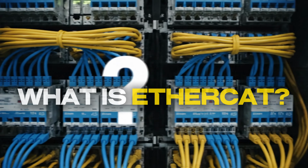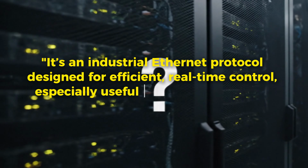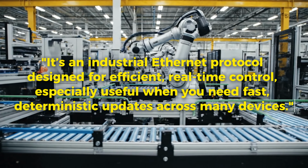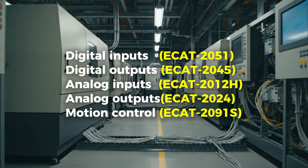So I think that we're ready to fully answer the question. What is EtherCAT? Well, EtherCAT is an industrial Ethernet protocol designed for efficient, real-time control, especially useful when you need fast, deterministic updates across many devices. And in practical systems, that often means EtherCAT networks built with modular hardware like digital inputs, digital outputs, analog inputs, analog outputs, and motion control. So if you're designing a system where timing matters, understanding EtherCAT and how to architect the I/O and motion layers around it is essential.